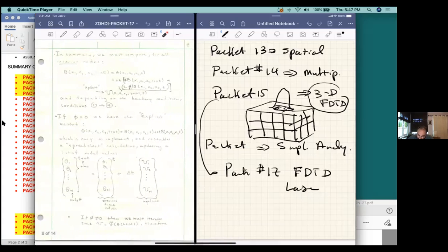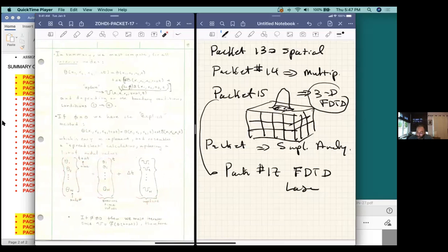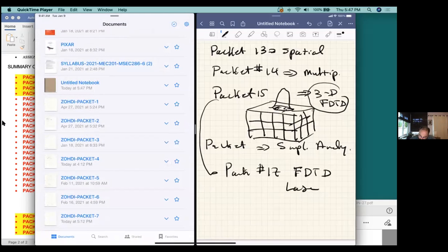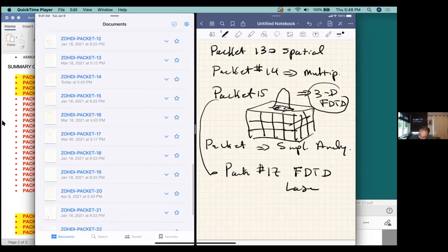And at the end, we get a spreadsheet calculation that says, look, the values at the nodes at time t plus delta t, the value of the nodes at time t, and the updates, and then we're basically able to step the problem forward in time. So again, another rather beautiful and succinct way of doing it that has, of course, become very popular in the heat transfer business.